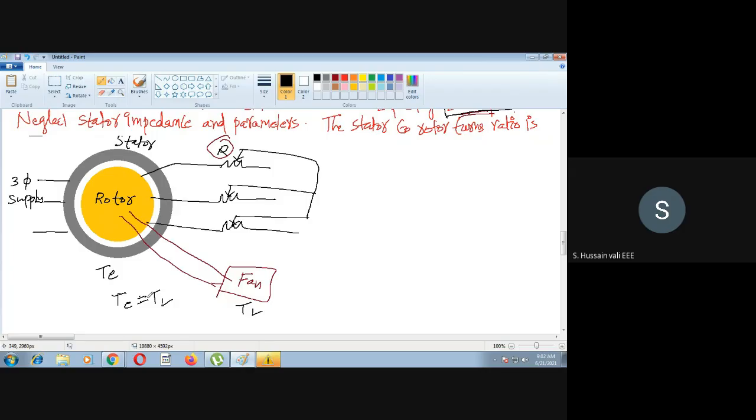So when the fan is at rest, then you need this equation. In the case of the fan, what is the relationship between load torque and its speed? This is important. How do you know what the relationship between load torque and the speed is? It is a relationship k n square. You may find out even on the net what the load torque of a fan is.